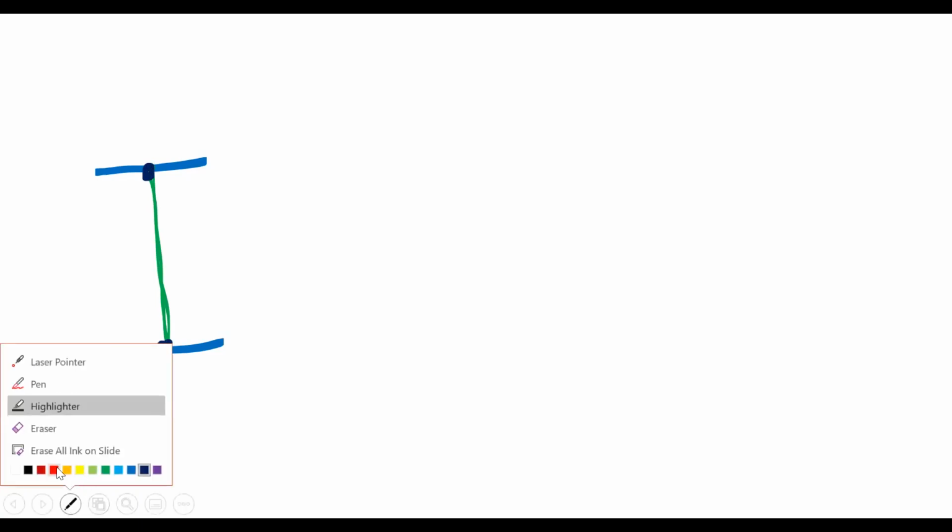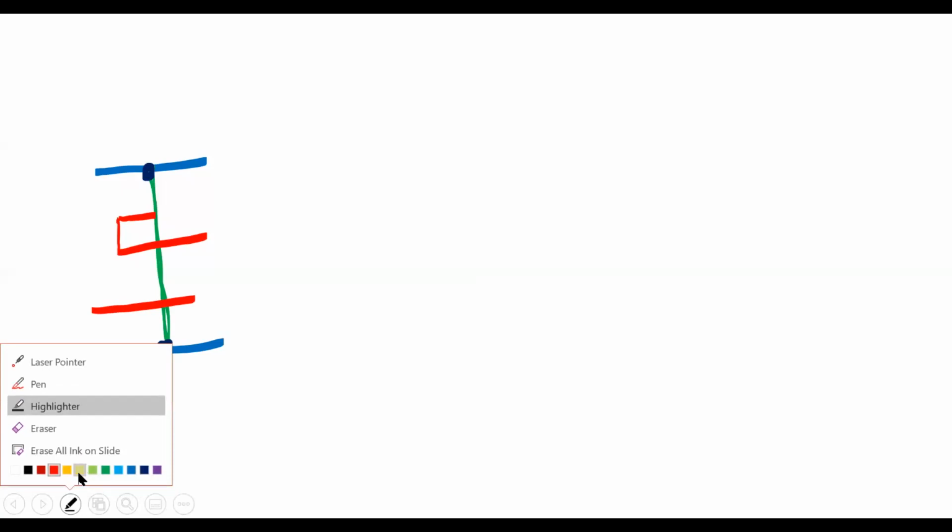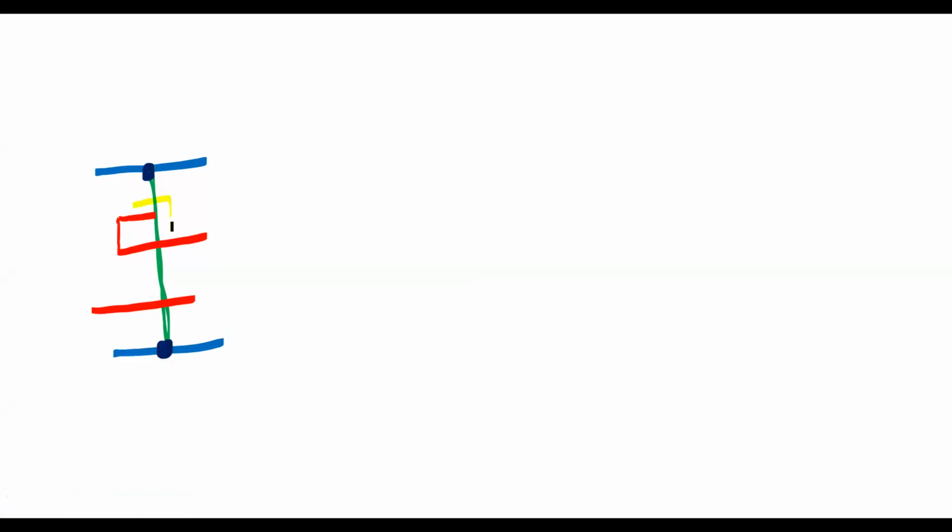One more is polysilicon, which is red color. There is one polysilicon, and you can run another like this for one more transistor. And now, the implant is to show the depletion MOSFET. And one more is the buried contact.